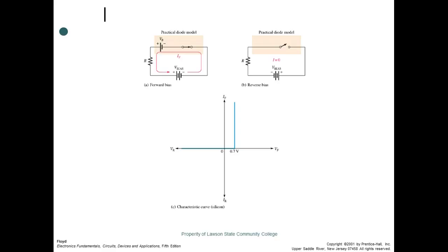No. Is it close enough so I can tell if something's working or not working? Yes. Plenty close enough. In fact, we used it the other day, right? We used the rated voltage on the transformer that said 110 volts to get 12.6 volts out. And we calculated 5.6 volts, and we measured 6.4, I think. So I think it was like 100 millivolts difference or something like that.